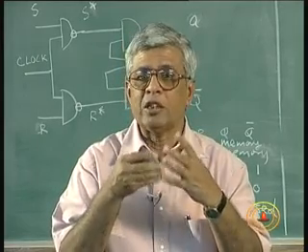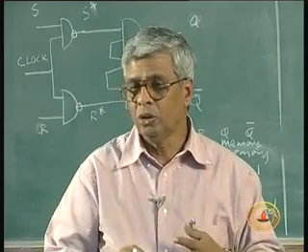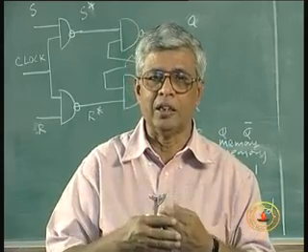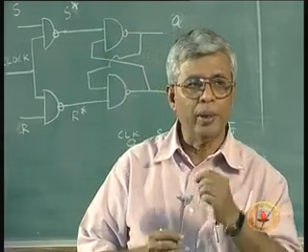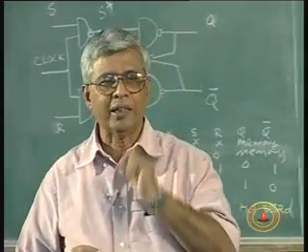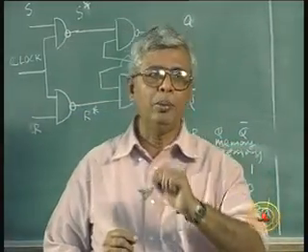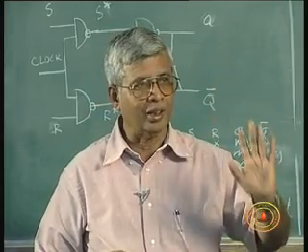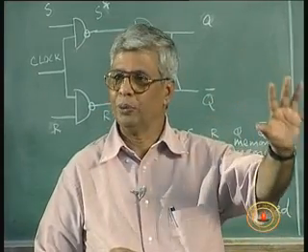If you have a reason to change the input, do it at that time. This is generally a good practice in any digital system design, in sequence circuit design. It is a good practice not to make changes in the input when the clock is high, because when the clock is high it can immediately affect the output, whereas when the clock is low it will wait for the next clock pulse, only then it will affect the output.